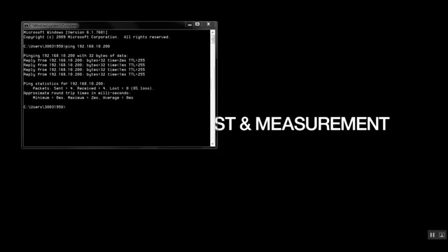Now that we have a working successful Ethernet connection with the power analyzer, our next step will be to set up the software pieces. The first software element we need to set up is GA10. This establishes connection with the WT500 power analyzer. I will select Run as administrator. Remember to always do this, otherwise the application will not have write access to its folders to save configuration changes.